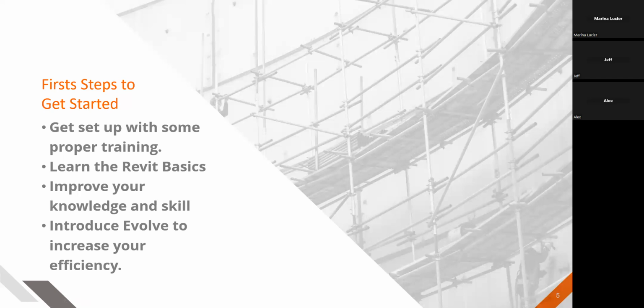Let's see. Can you run calculations in Revit? Revit does have some analyze tools. You can run calculations for all mechanical, plumbing, electrical, so you can do voltage, you can do pressure drops, CFMs, and a whole bunch more. Obviously, you have to have a set system. So if you get your systems done right and you model everything correctly, you can run and analyze your systems that way. I would actually go through an engineer to confirm all that, but it's definitely a great quick glance look to see what those look like.